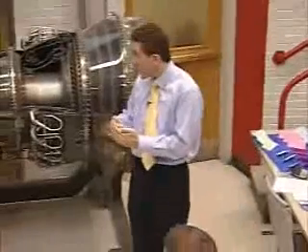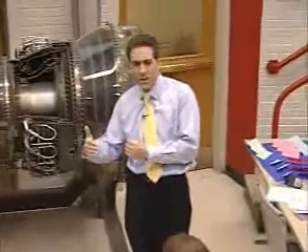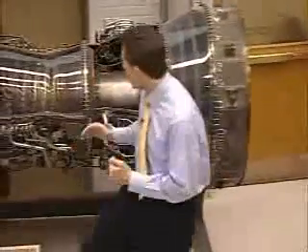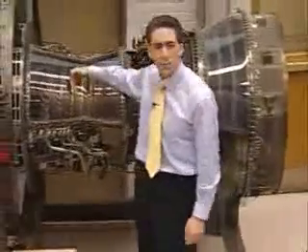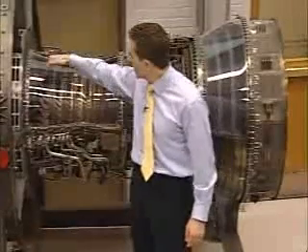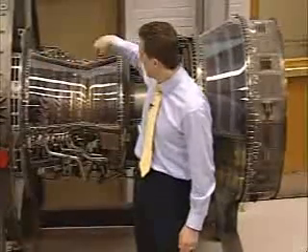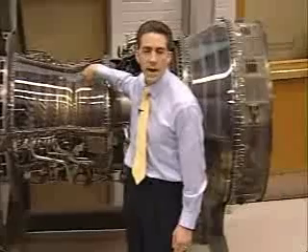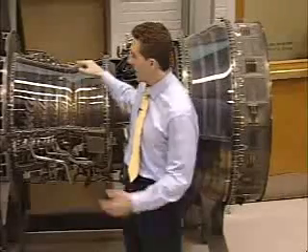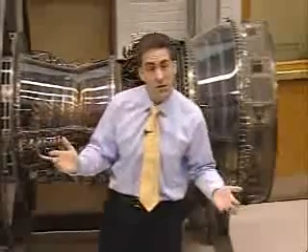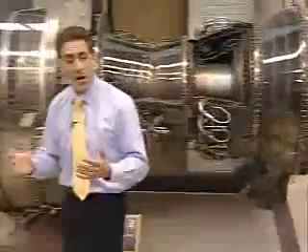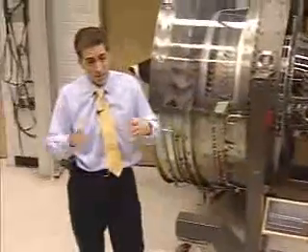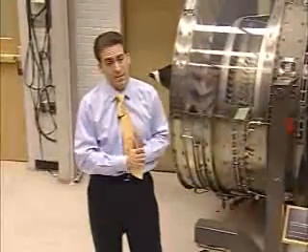And then what you typically do when you design, you say, I'm going to try and spin it a little faster or push that a little more. Or maybe I'll turn the flow a little bit more than I did in the past so I could eke out a little bit more pressure rise per blade row. And if I'm really good and I do that for all my blade rows, maybe I don't have to carry around one of these back stages anymore. And now I shorten the whole engine. It gets lighter, improves my range. So you do it all at once, but with some knowledge of what you've done in the past.